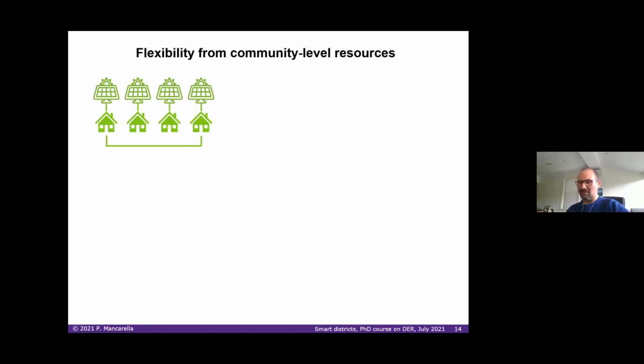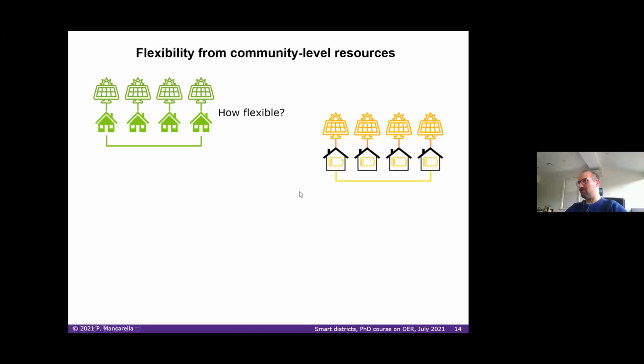You're not using it in a positive way. So not really too flexible. That's why you add batteries. Instead of curtailing, because I need to export and do not have sufficient consumption when there's lots of PV production, I store it, and then I decide when to sell it.